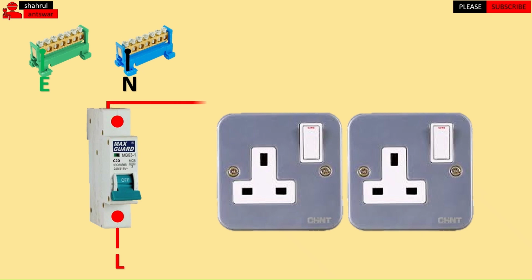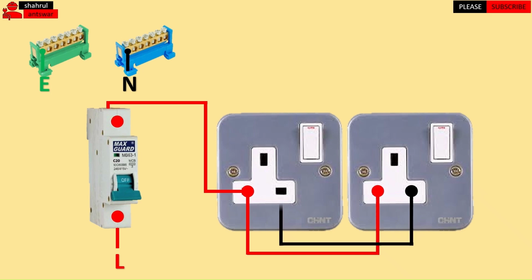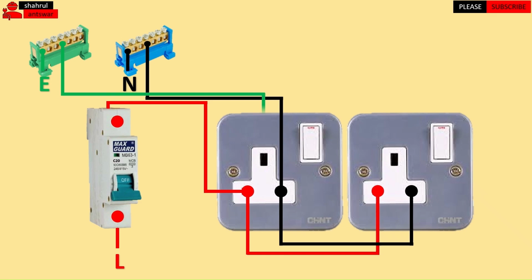The 2 outlet socket units are connected in parallel to each other, and the connection will end at the second outlet socket. The maximum number of outlet sockets when connected radially is only 2 units. If it is necessary to use more than 2 outlet sockets, a new circuit must be created using a new MCB.